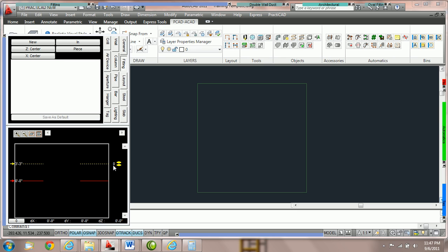So what we need to do is create a 20-foot mark, and we need to create it as relative bottom. To do that, I'm just going to click on the notation here, and I'm going to type in 20 foot and hit enter. Now, right away, we don't see the relative mark, and the reason why is because it's actually now at the top of my elevation box. As we add relative marks and new elevation points, they're going to go above and below our current elevation.